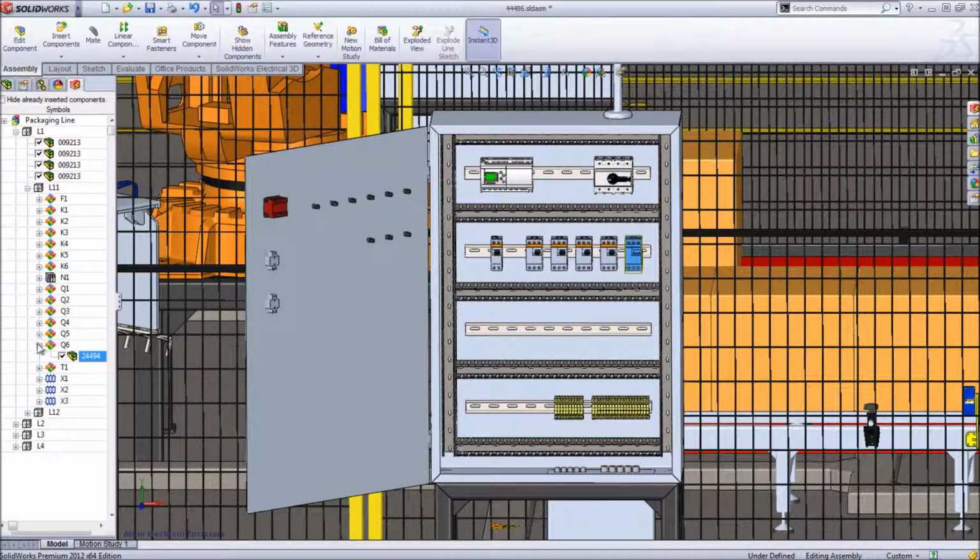You can also simply right-click on the transformer and select Insert. If the part is properly defined in the library, the software will automatically retrieve the part, meaning you don't have to browse several directories or folders to find the right SOLIDWORKS model. Components snap and are also easily attached on the DIN rail using SOLIDWORKS MyMates.